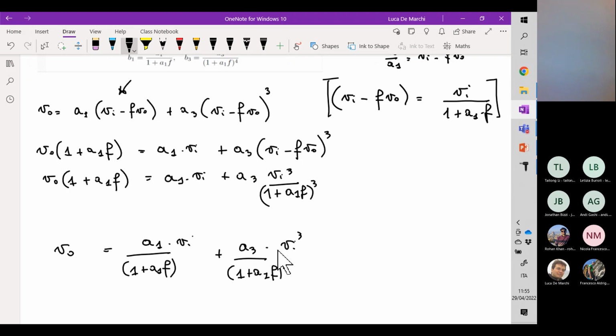So with a phase margin equal to 90 degrees, you see the actual value of A of j omega over A null is this one. When you have a 60-degree phase margin, you have a very small overshoot, and then you get to the original DC gain in correspondence to omega null.